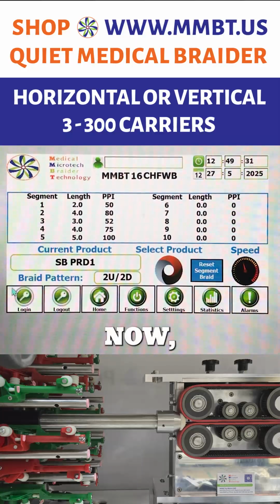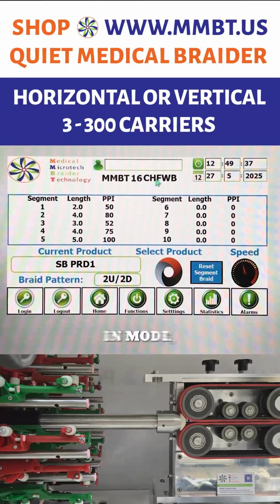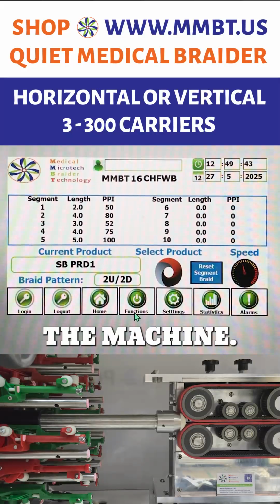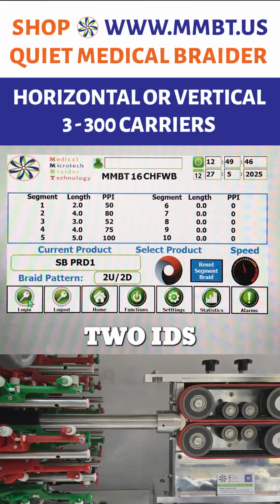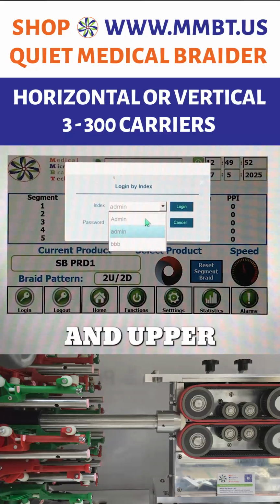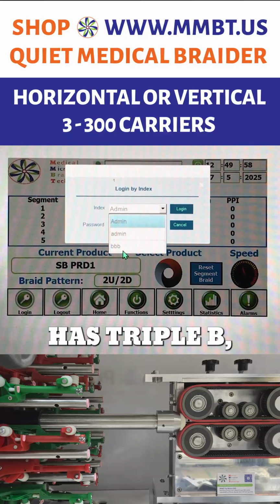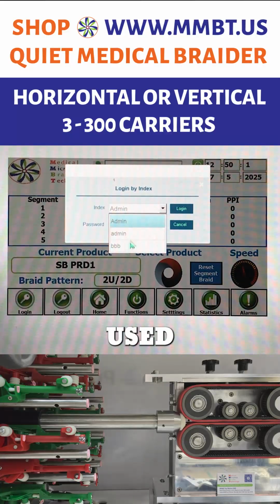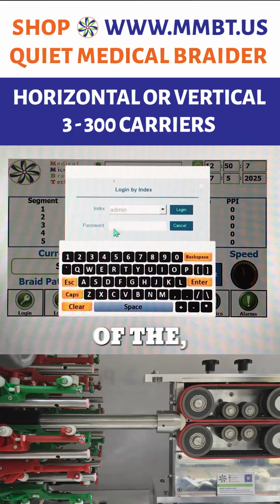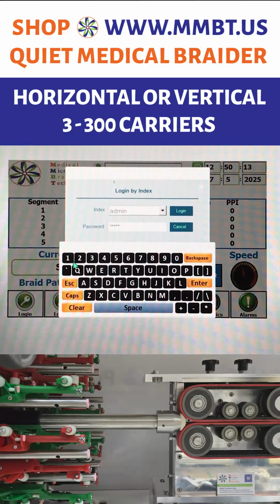Now the software itself has 3 different modes. Currently I'm in a non-logged in mode, which means I'm still able to load a product and to run the machine. The other 2 IDs, which are found under login, are lowercase admin and uppercase admin. Those are the 2 we can use. The one that has triple B, that's proprietary and never used. The lowercase admin will give you access to all of the different features of the software. So I'll log in with this.